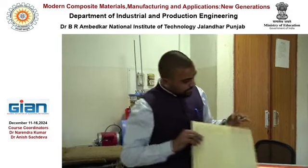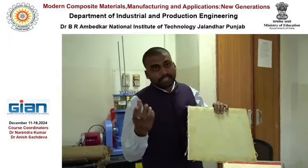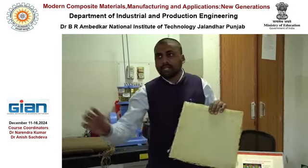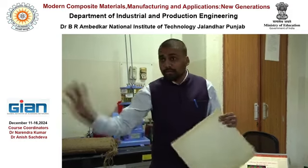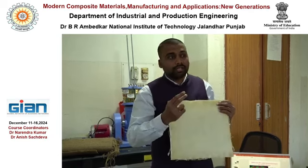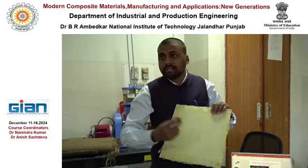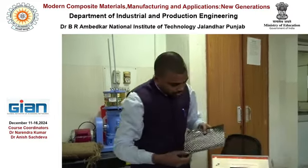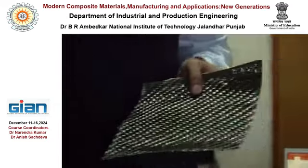But what happens is that if I am changing the weave structure, let's say I am using the same fabric in compression molding and the same fabric in vacuum bagging, producing the same composite material with the same fiber volume fraction. But since your weave structure is different, it will lead to variation in the fiber volume fraction at the micro level. So at some places where you are having the floats, it may lead to the formation of resin rich areas.